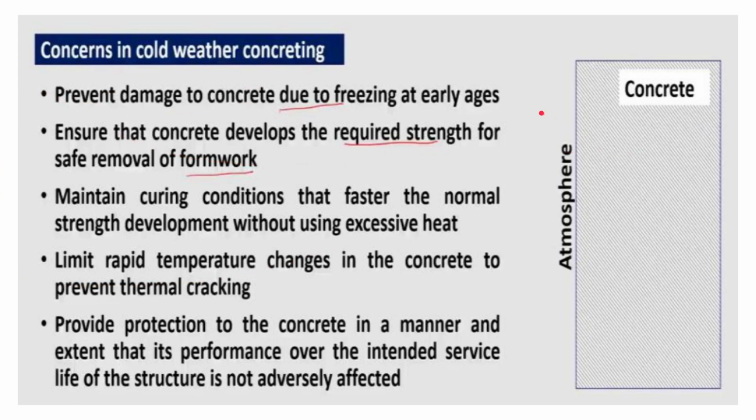Based on the discussions, these are some of the concerns associated with cold weather concreting. Firstly, we need to prevent the damage to concrete due to freezing at the early stages. Secondly, we need to ensure that the concrete develops the required amount of strength for the safe removal of formwork, because formwork is mainly used for giving it the shape. If the strength is not developed, the shape will also not be developed, so there is no use of the formwork provisions.